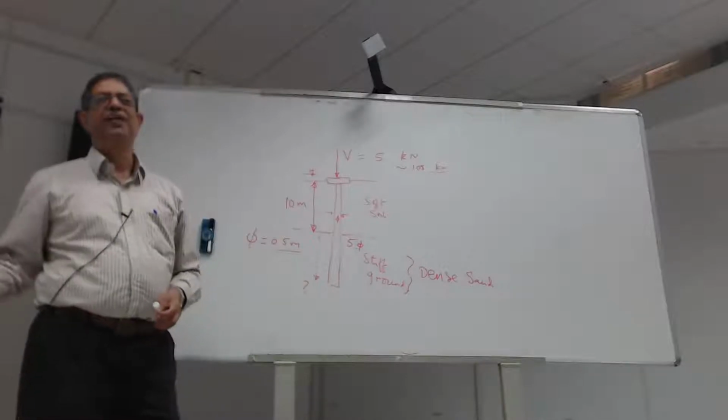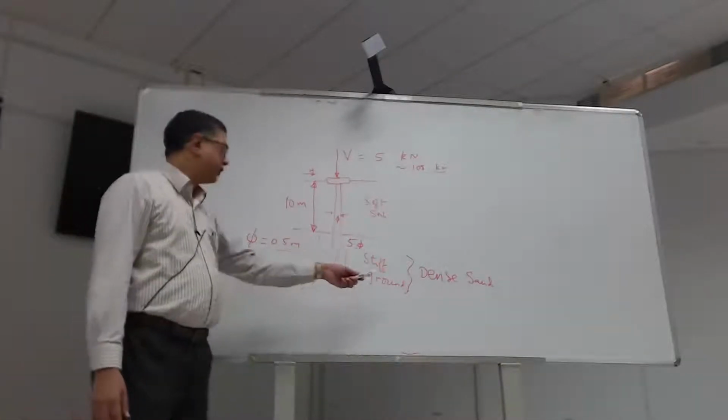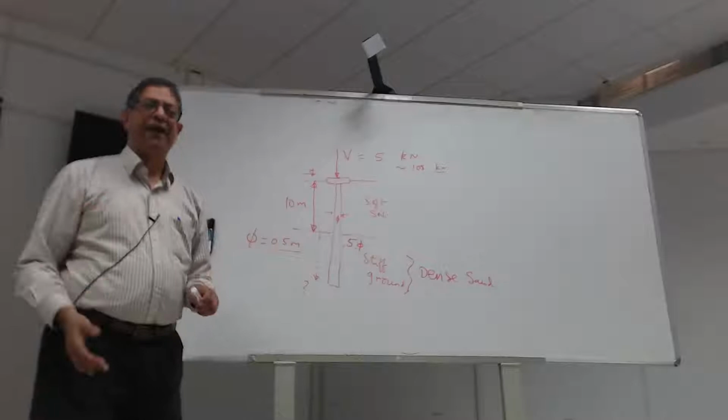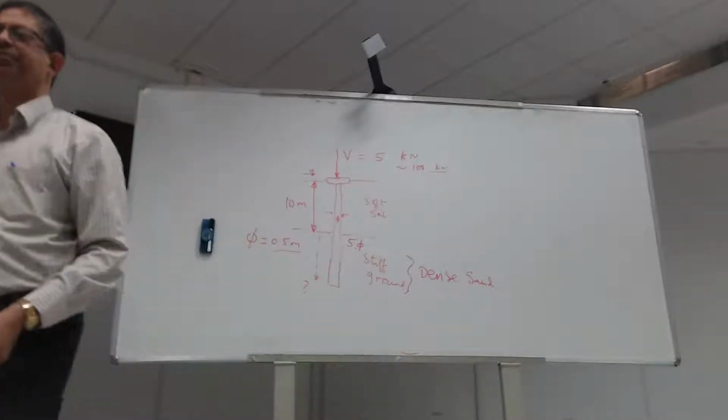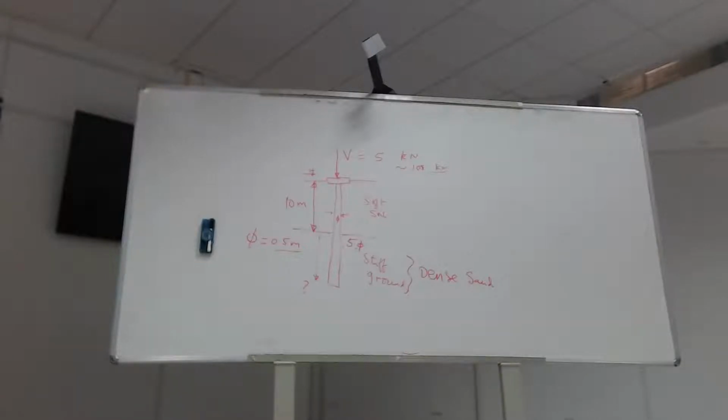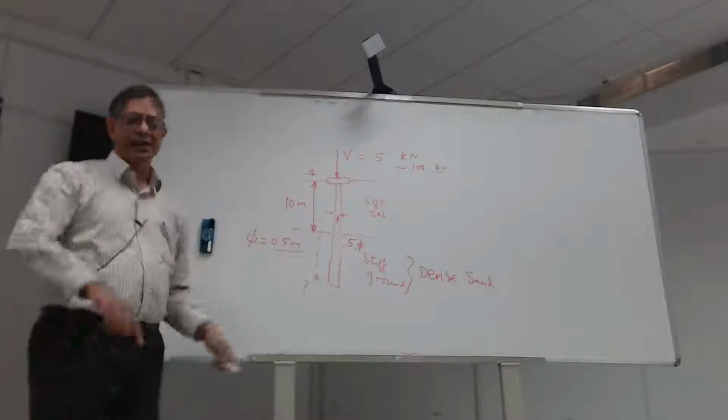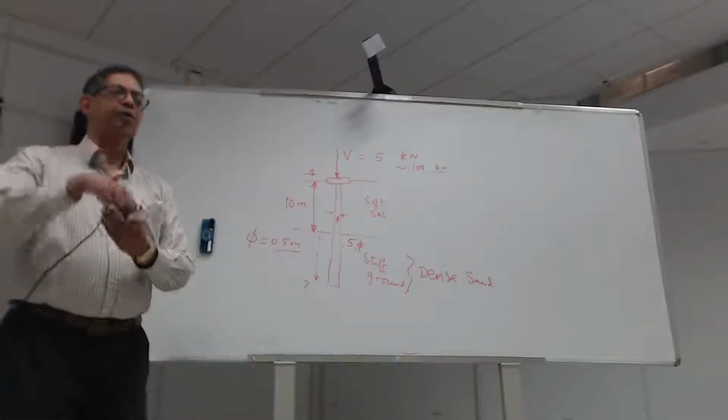Usually that governs how deep you can go. But if the soil is a bit iffy, you can reach 5 diameters reasonably easily. Rock, of course, you cannot do any of this. If this is the bedrock, you basically bore a hole and you rock socket the pile.